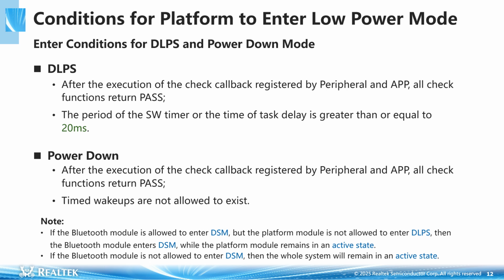Note: if the Bluetooth module is allowed to enter DSM but the platform module is not allowed to enter DLPS, then the Bluetooth module will enter DSM while the platform module remains active. If the Bluetooth module is not allowed to enter DSM, the entire system will remain active.